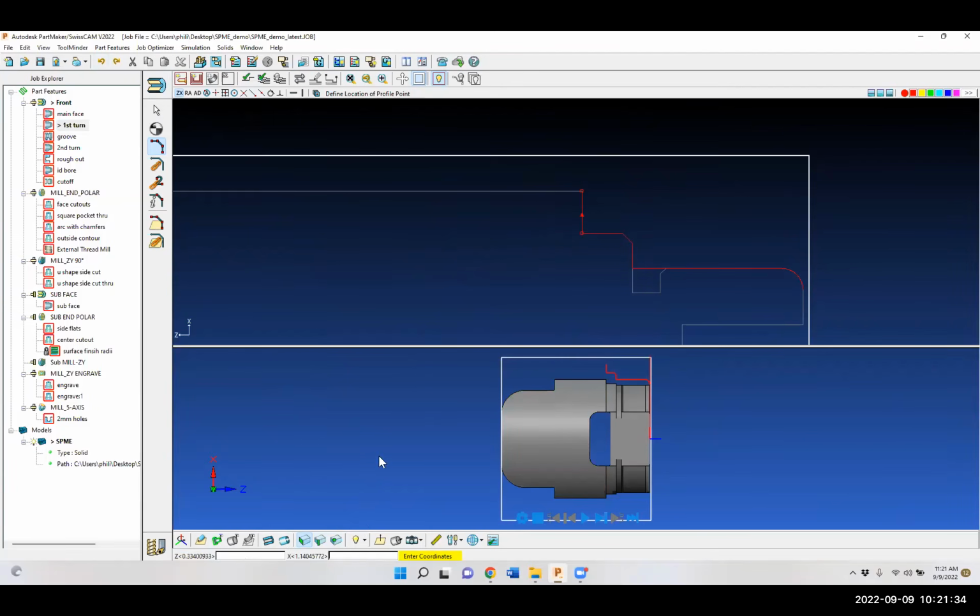So the first X vector is going to be 10th thou below. That'll be 1.24. Then I want incremental motion for Z, and the at symbol allows that. So I'm just going to go at 0.01 and put my edge break at 1.25. You can see that I'm breaking the edge, and then I'll just sweep the tool along the chamfer to remove any possible burr.